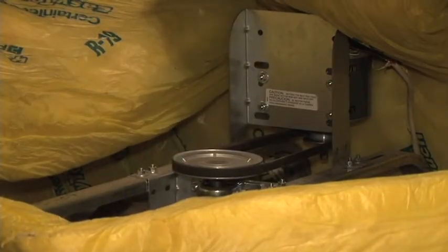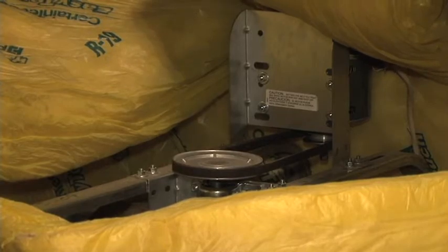We'd build a 4-sided box, seal it at the ceiling, and then put a 5th piece of rigid foam on top, making sure it's well sealed with weather stripping. And then we put something heavy like a brick on top. Then in the summertime, we take the brick off, we take the lid off, and we can turn on the fan and cool the house.